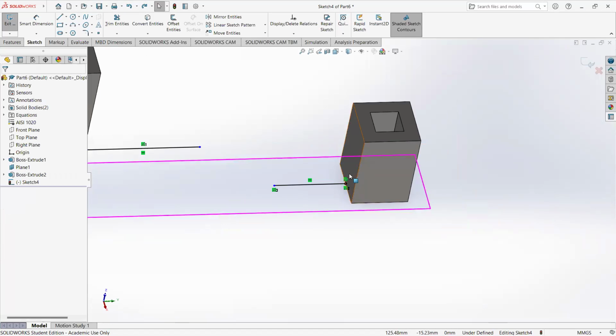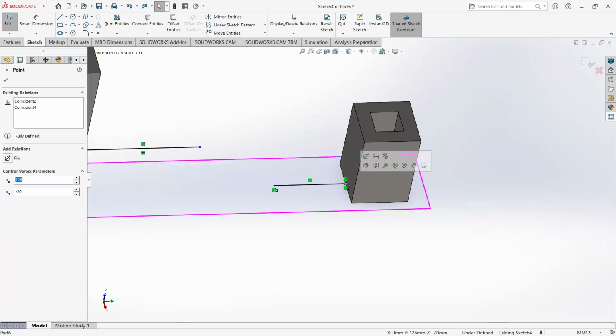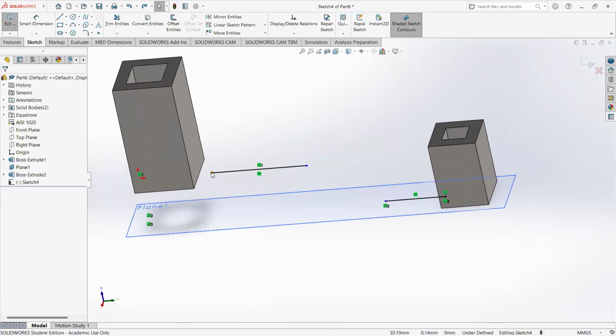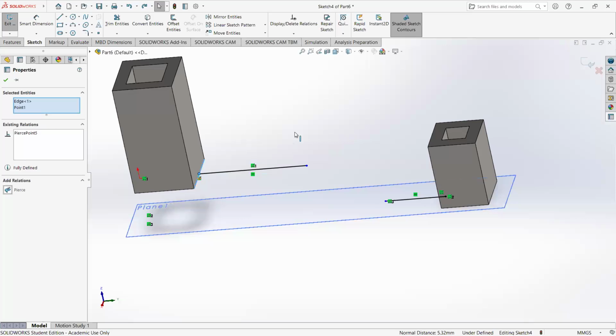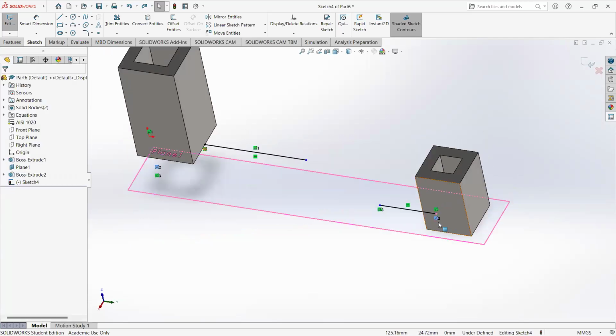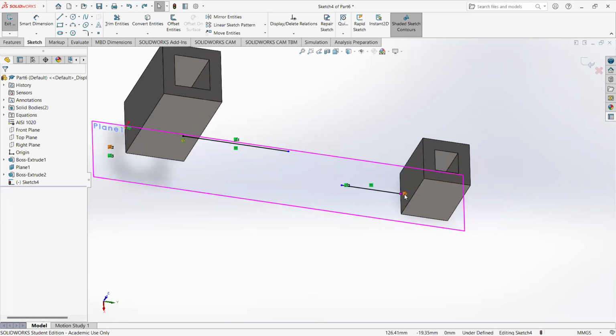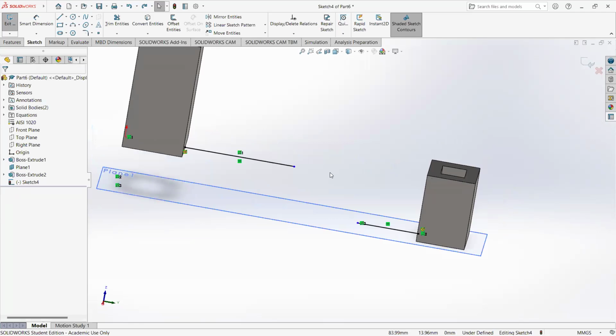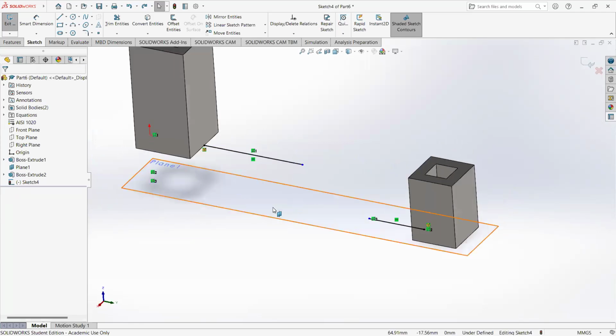In layman's terms, that's just another way to make sure that this is on this surface, rather than just coincident with one of the lines. But for now, it doesn't look like it wants me to do that. So now that one, it did let me pierce. In fact, that one I can't do coincident. I have to do pierce, maybe because they're on a different plane. So I'm going to delete that. Oops, I want to delete probably that one. That's right, because I grabbed the vertical here. Let's grab this one and pierce, just to make sure that my sweep is happy when I go to use this, because what this will end up being is the path for my sweep.